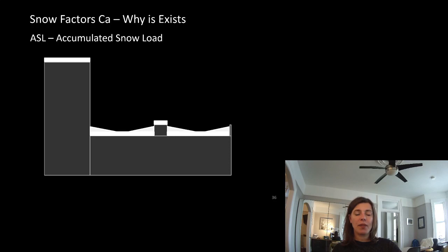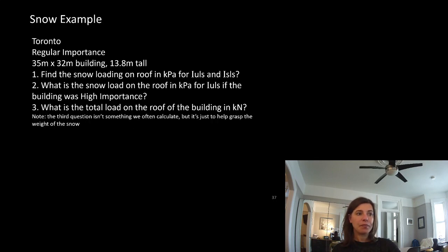So it is something that is very important that you know about, but I'm not going to make you calculate it. You're going to use 1 as your snow load accumulation factor, not 0. When I say don't worry about it, it doesn't make it 0, because if you use 0, you're going to wipe out your snow load equation. You're going to use 1 when I say you don't have to worry about it.